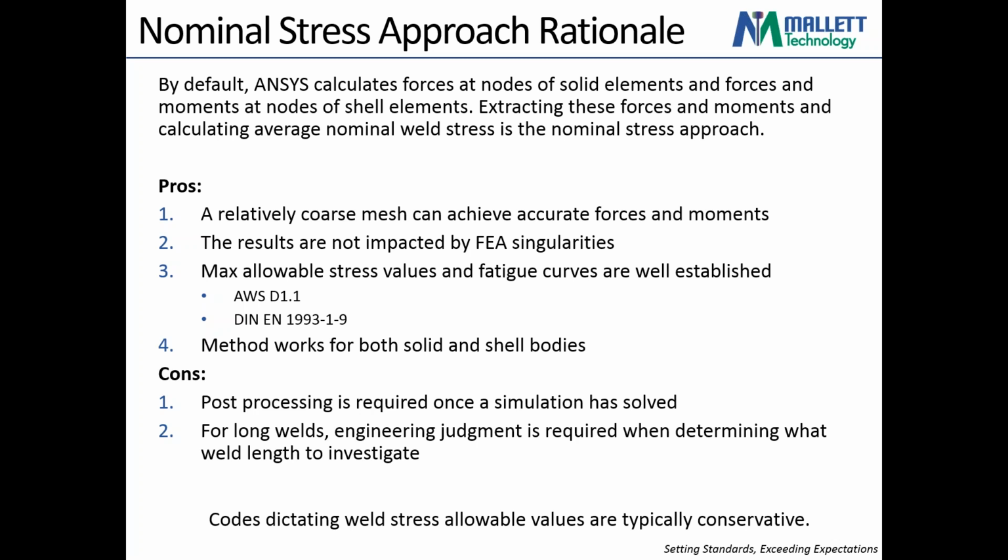The idea behind the nominal stress approach is the forces and moments that you extract are smeared throughout the defined weld length, and then you use that smeared approach, figure out the worst-case stress for that weld length, and go from there. The rationale being that essentially welds immediately next to each other will help participate in resisting some of the load.